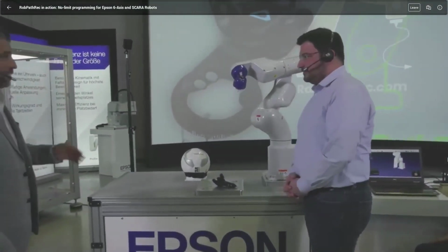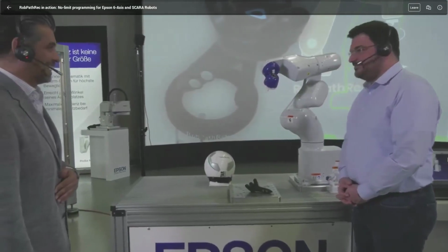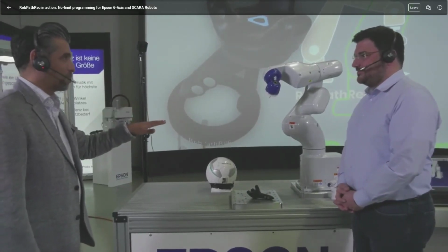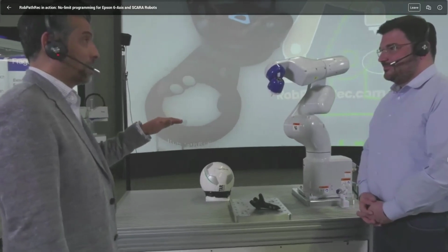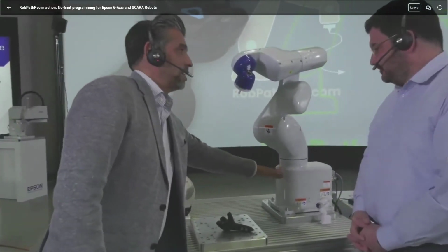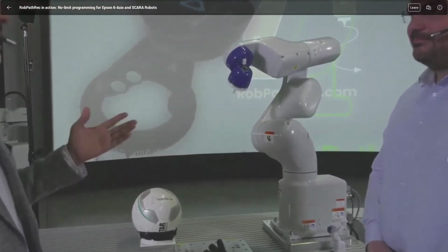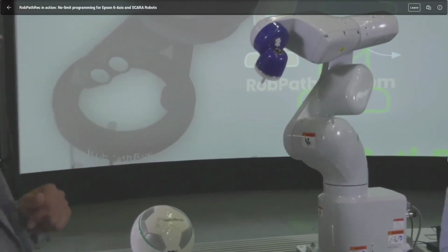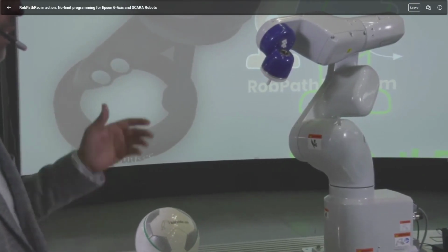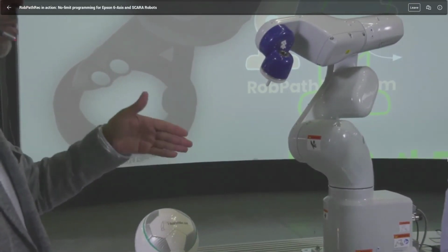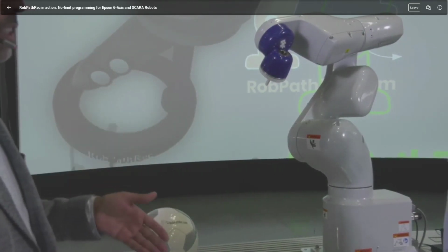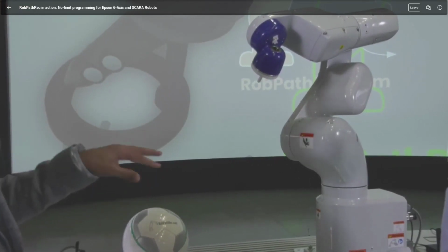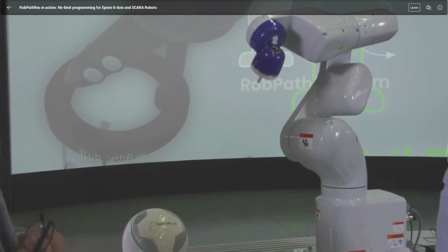Yeah, that's great. So before we start, let me also introduce our 6-axis robot. Here we are talking about an entry model as well, with built-in controller. We call it VT6, VT6L because of the arm length. The robot can carry up to 6 kilograms and has an arm length of 900 millimeters. It can be mounted in different ways, like tabletop, wall mount, or ceiling mounted. It also exists in clean room, IP67, and DC version with 48 volt. We normally keep the robot in stock, and we can dispatch within 4 weeks if required. So this is the robot side.